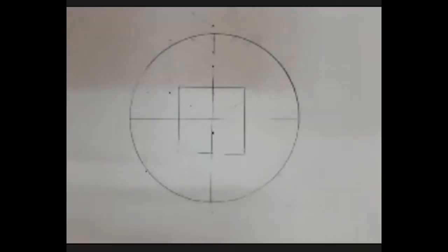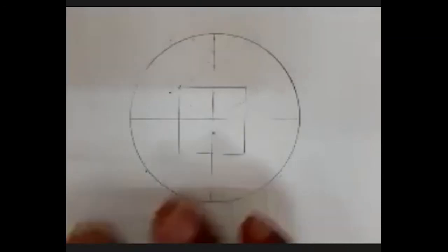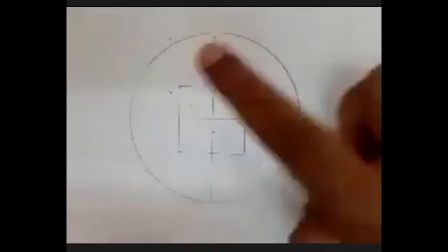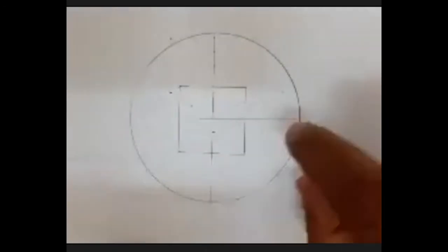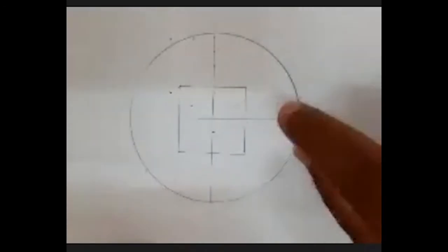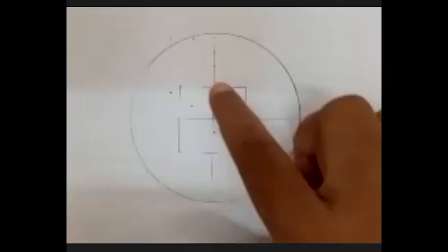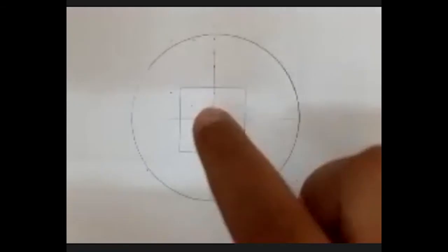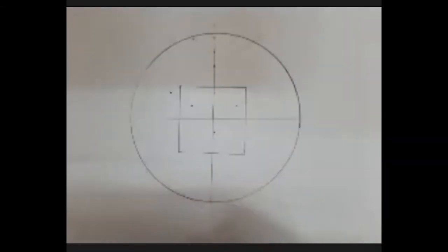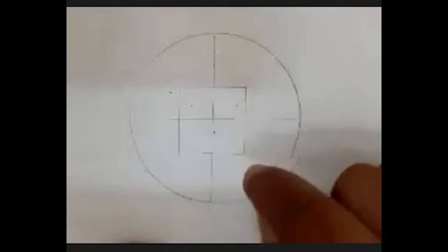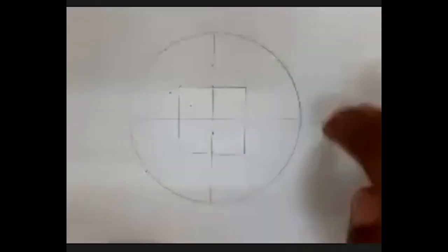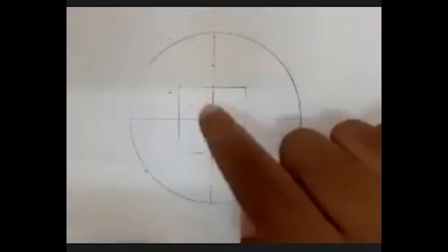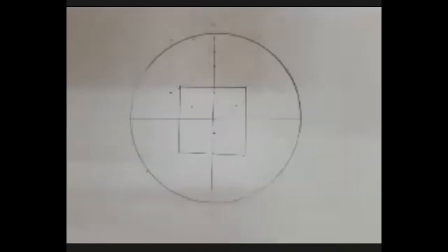So when I see this in the top view, the diagram looks like this. I have a cylindrical slab of 100 mm diameter, and the thickness of this cylindrical slab is 30 mm. Then I have a square prism of 40 mm side, and its height is 50 mm. But when I see this whole thing from the top view, I can just see a circle as well as a square which is placed centrally.